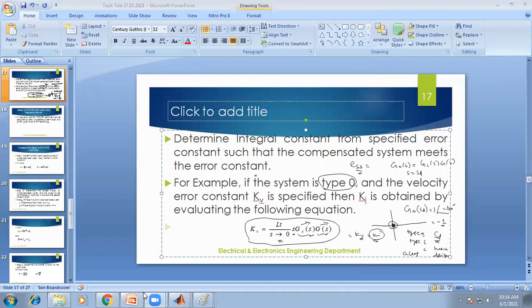Okay, sir. Actually, the design part, the formula, and the procedure are all available in the textbook. The main motto of this session is sharing that knowledge, so that hereafter faculty or researchers may know how to design Kp, Ki, Kd values. Many researchers use Ziegler-Nichols and Cohen-Coon. When we use the Ziegler-Nichols method, we want the open loop response and we need to calculate L, the time constant, and so on.